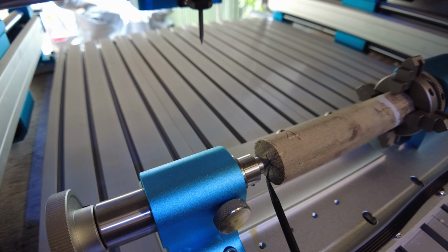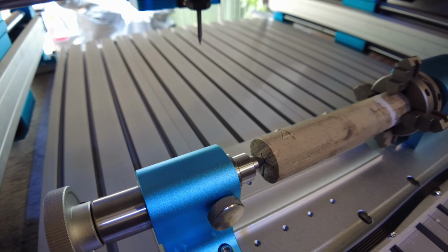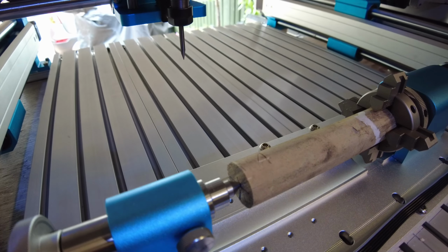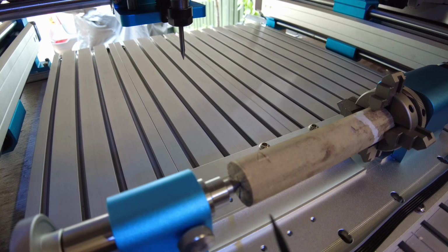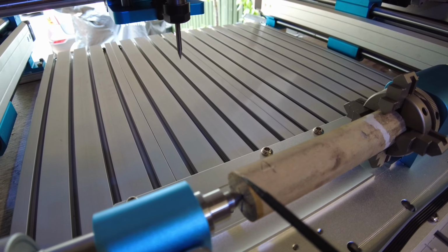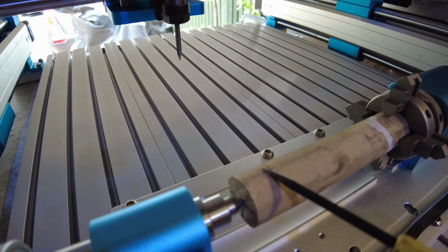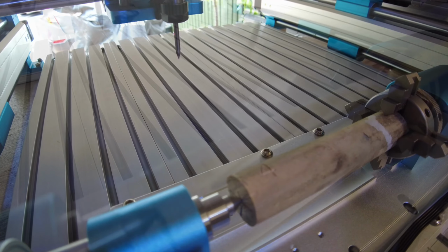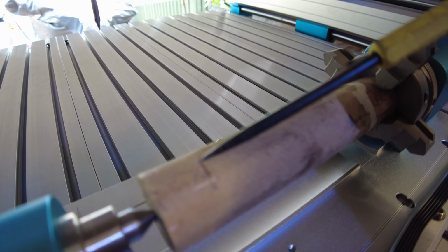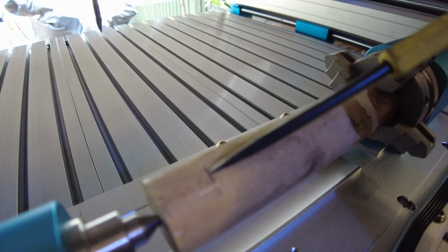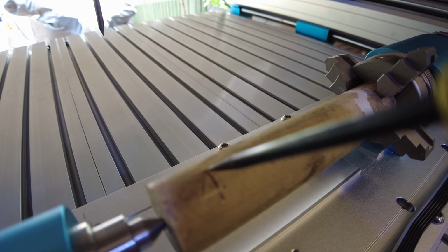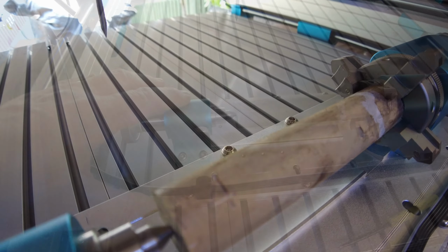Well, obviously when you zero on the drawing, the actual number is in the centre, because it's a flat plane that it shows you. So if you look at that line there, number 4 is exactly in the centre, but on the opposite side to where I zeroed off. Because it is a V carve, it'll lift out the corners, and it's done that really nice and crisp, and it's probably about a mil and a half deep.